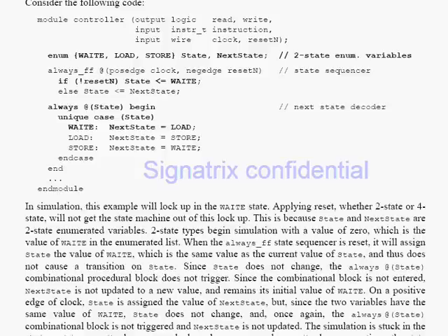We define state as a two-state variable, so state is having 2'b00 definitely, right? Because this is a 2-bit variable, and when you are resetting, it will come to some known state as 2'b00. So already your state is at 2'b00, and when reset comes, your state is wait.